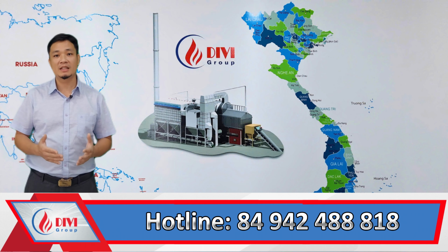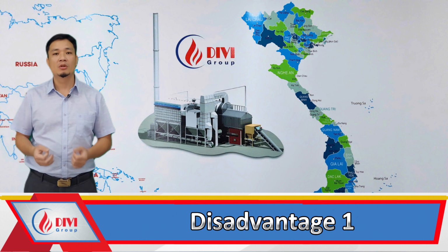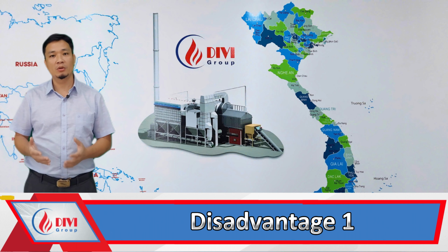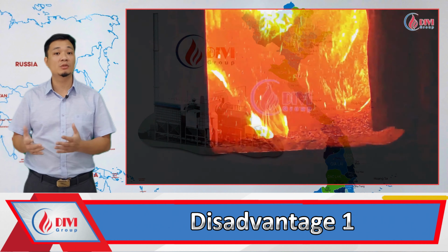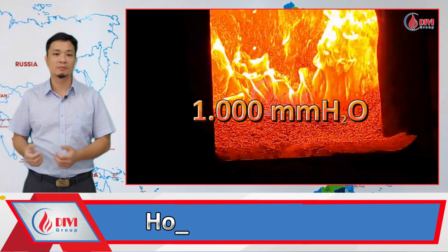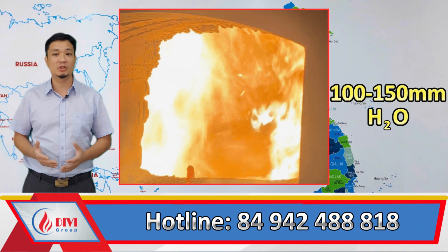Dear viewers, everything has two sides. We've seen the advantages. Now let's look into the disadvantages of this fluidized bed material. Disadvantage 1: electricity consumption for the primary air supply fan increases dramatically. To keep both the fluidized bed material and the fuel particles suspended, a strong upward airflow must be generated. As a result, the fan's pressure head typically needs to reach 1000 mm H2O or more. In contrast, if no fluidized bed material is used, only 100 to 150 mm H2O of pressure would be sufficient.